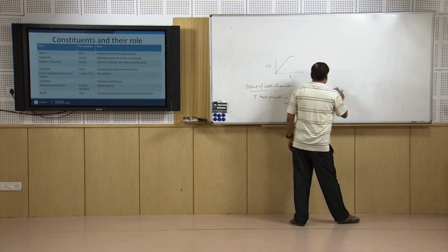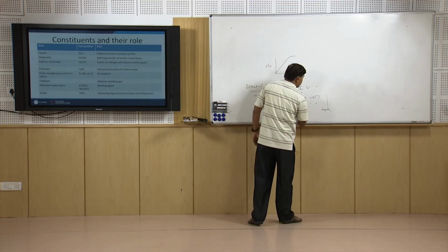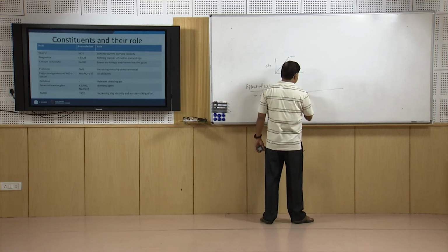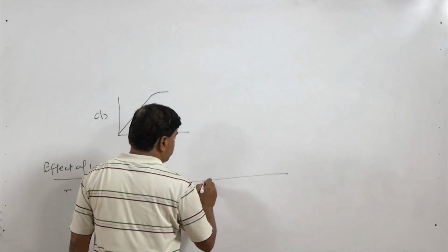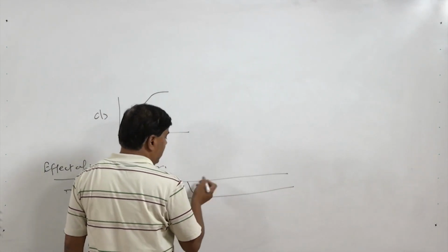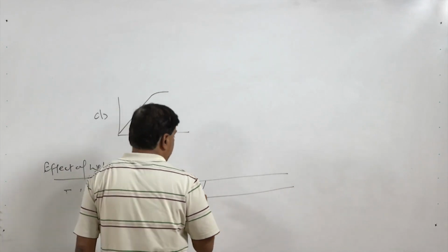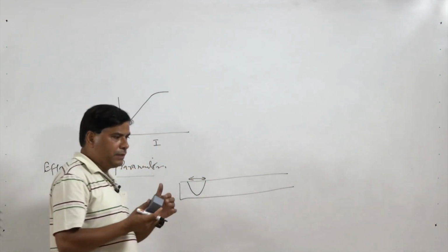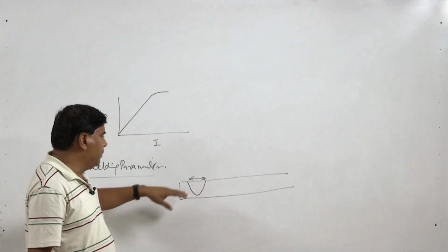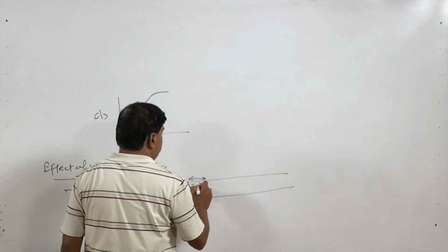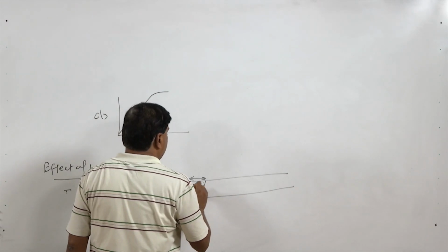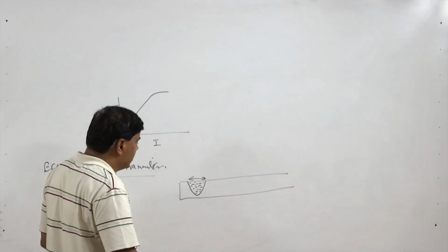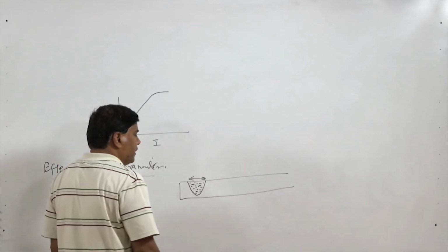this welding speed directly affects the amount of heat being delivered to the base metal per unit length. So, if the speed is very low, then heat will be delivered continuously over a small area and it will result in a large weld cross section. Maybe depth may be limited, but it is very wide. By reducing the welding speed, we can keep on feeding the heat over the molten metal. This does not help much in achieving deeper penetration, but increases the width of the weld, thereby increasing the cross sectional area of the weld.